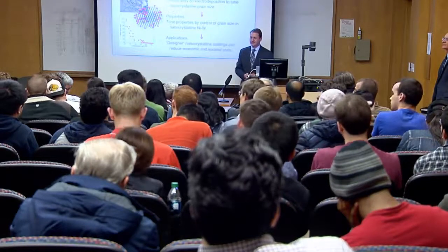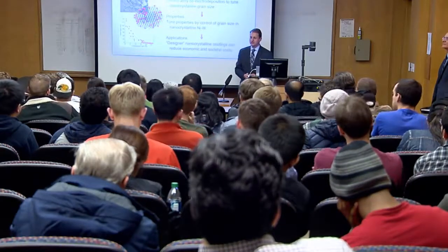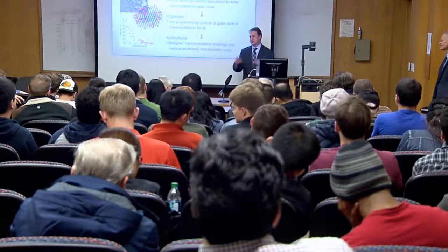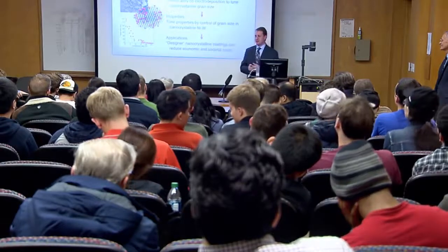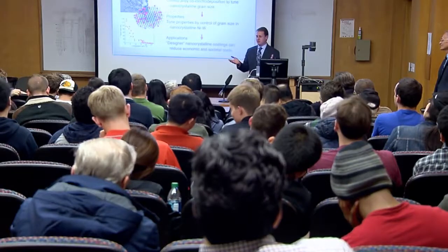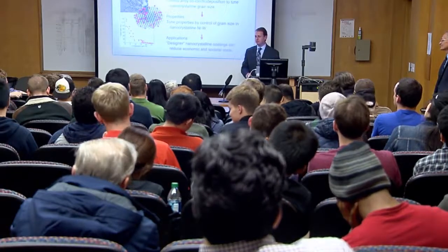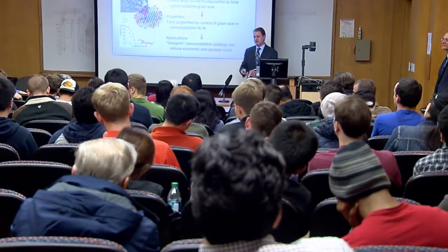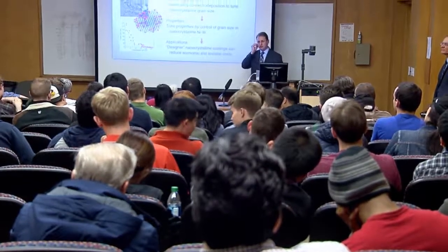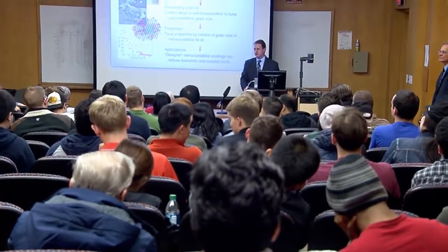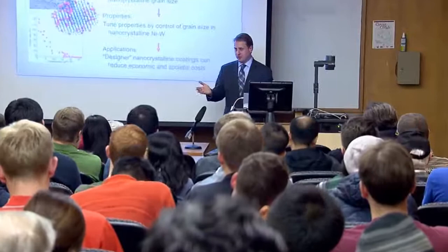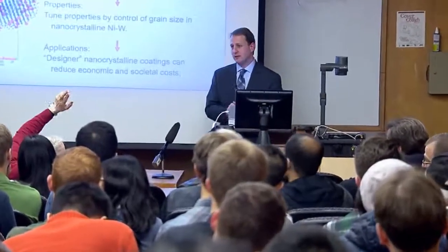So how do you compare this to yours? Well, I think the sort of cop-out answer is that this is the opposite side of the phase diagram, and it's a different base structure, so I don't think you can just look for the same behavior because the elements are the same. Right, and the homologous temperature is completely different. I'm on the nickel-rich side where tungsten is the slow diffuser, so I don't think I have a smarter answer than that, but I'm not looking for symmetry on those two sides of the phase diagram.